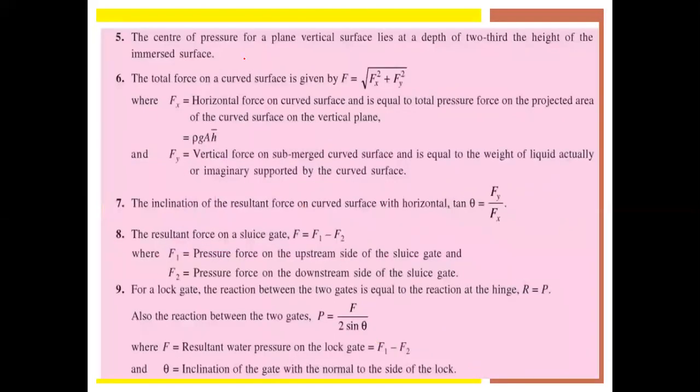Next, the center of pressure for a plane vertical surface lies at a depth of 2/3 of the height of the immersed surface. Next, the total force on a curved surface is given by F equals root of Fx square plus Fy square.